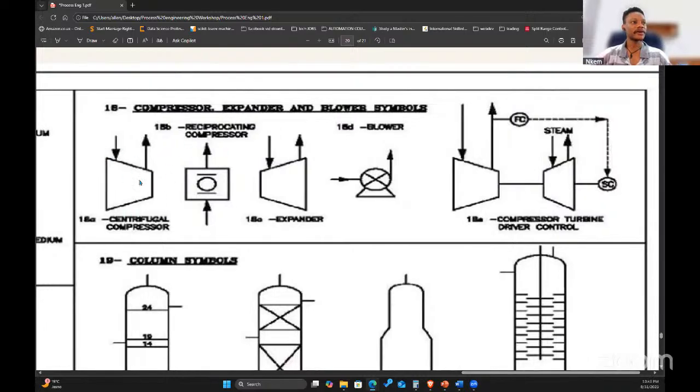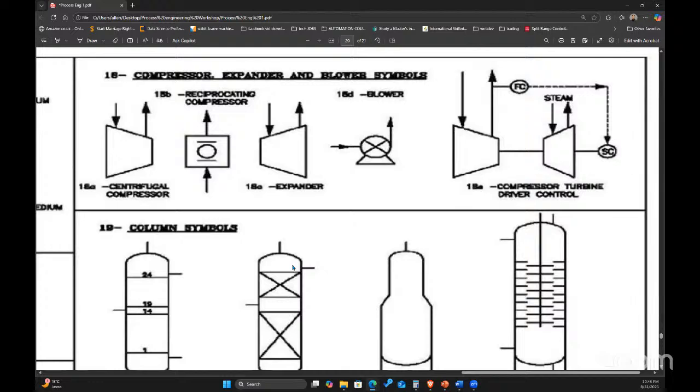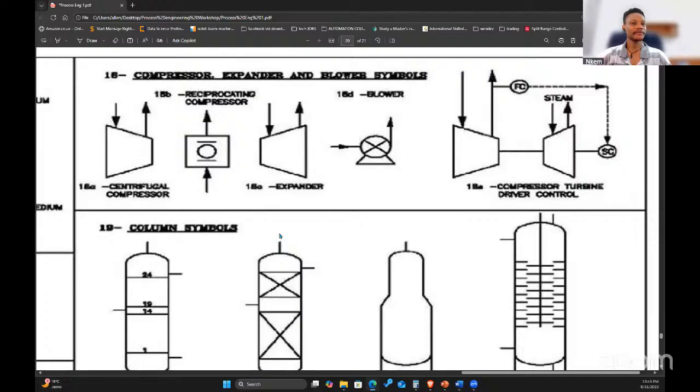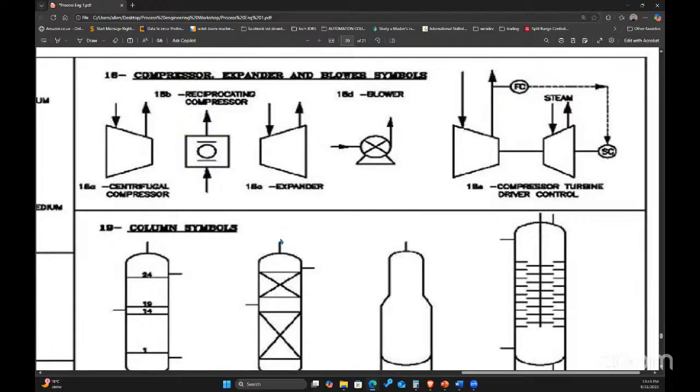This is your centrifugal compressor. And for a compressor, remember you are compressing something, right? And when you compress, what happens? Can you try to remember Charles' law, Boyle's law? What happens when you do compression? Can somebody say it before we go ahead? Basically the pressure increases. Is that correct? Okay. Pressure increases, and what about the temperature? Yeah, the temperature also will increase when you compress.